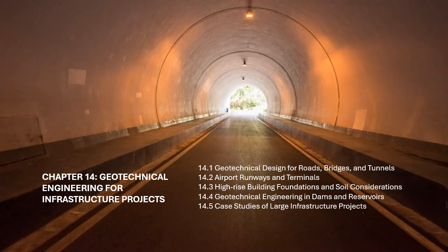Seismic considerations. Seismic activity can have a significant impact on dam stability. Geotechnical engineers assess the potential for seismic loading at the dam site and design the foundation to resist seismic forces. This may involve incorporating additional reinforcing elements, such as shear keys or flexible joints, to allow for movement during an earthquake.